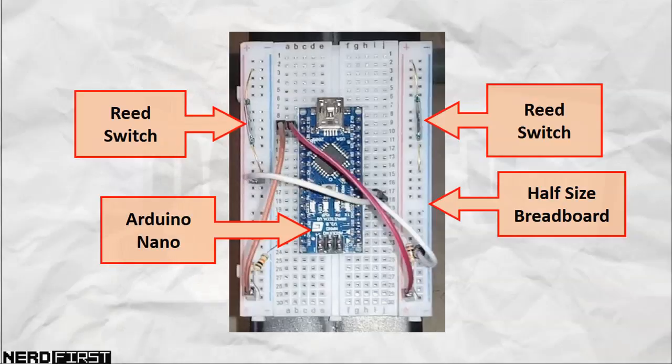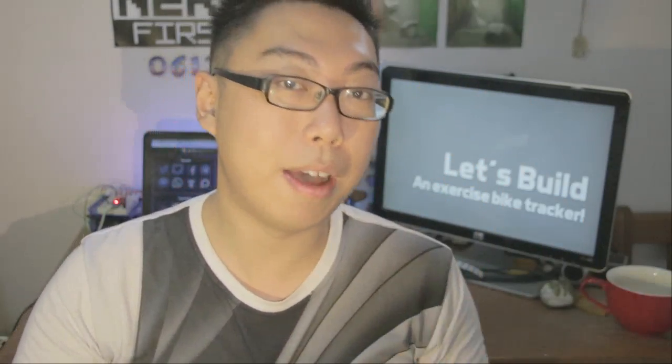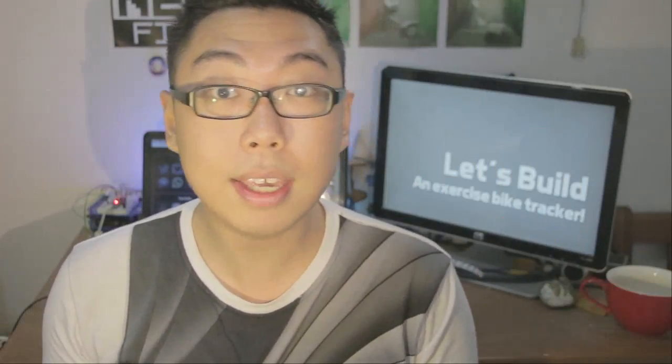Of course, what that means is I need to have one magnet on each pedal, and as a result, I'm able to detect every half turn of the pedals, because every half turn, one of the magnets is going to come near one of the reed switches. Of course, I have these on different pins, so I'm able to find out whether it's the left pedal that's down or the right pedal that's down, and that's really nice.